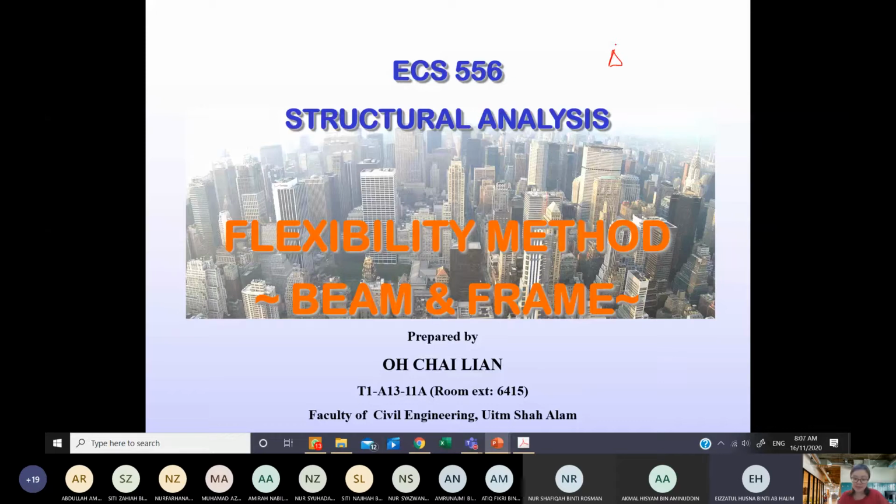If you still remember, delta is the displacement. For trusses, in the virtual work method, we use this equation, summation nNL over AE. Now when we are looking at beams or frames, we are dealing more with bending moments, so the displacements that we will use later will be integration of mM over EI. We are going to use the integration later for beams and frames.